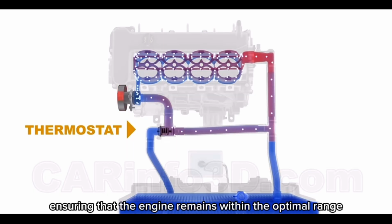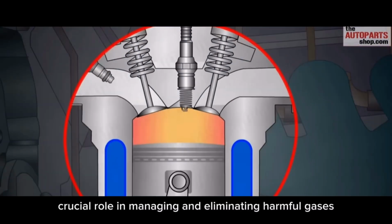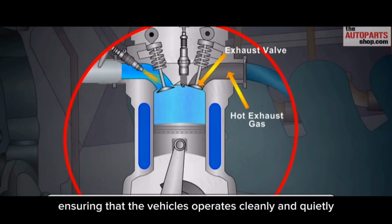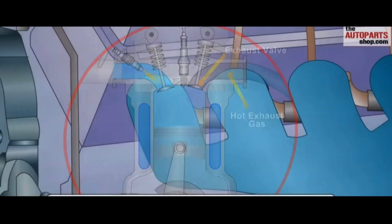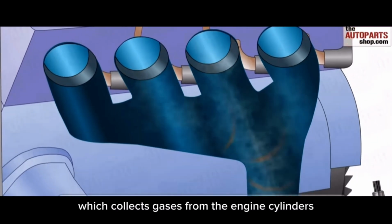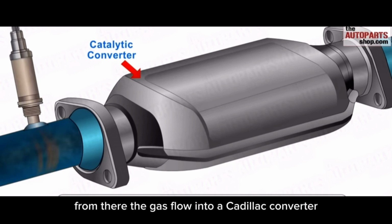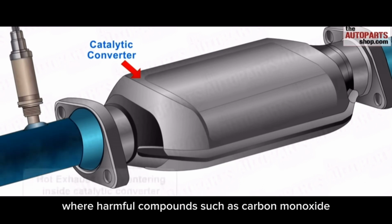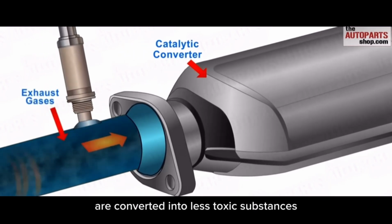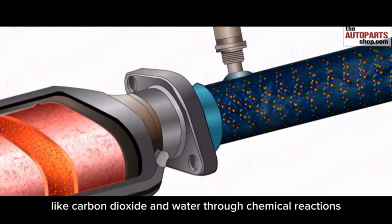the optimal range. The exhaust system plays a crucial role in managing and eliminating harmful gases produced during combustion, ensuring that the vehicle operates cleanly and quietly. It begins with the exhaust manifold, which collects gases from the engine cylinders and channels them into a single pipe. From there, the gases flow into a catalytic converter where harmful compounds such as carbon monoxide, nitrogen oxides, and unburned hydrocarbons are converted into less toxic substances like carbon dioxide and water through chemical reactions.